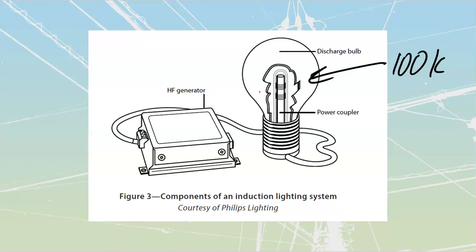These ones over here have a ridiculously high frequency, which means that they can induce, EG is equal to BLV, voltages into a lot of surrounding cables or other components. Note that it's off of velocity, and it's the velocity of this, not the flux density, but the rapid back and forth that can really cause a lot of generated problems. If you put these things close to electronic copper conductors, such as Cat5 cables or telephone cables, they will buzz out. You're just going to have so much interference as a result of these things being nearby. So be careful with where you place them.